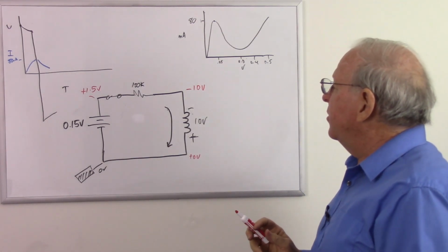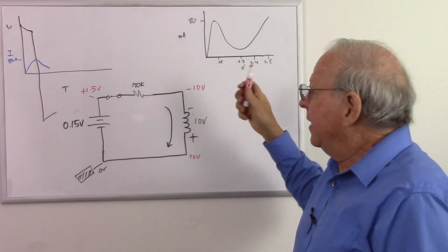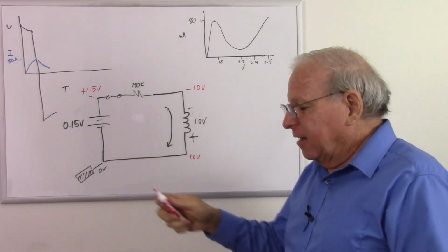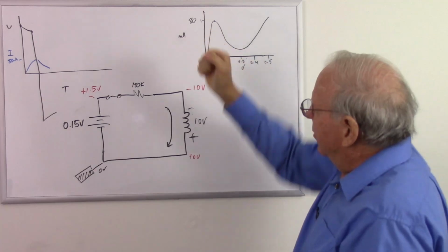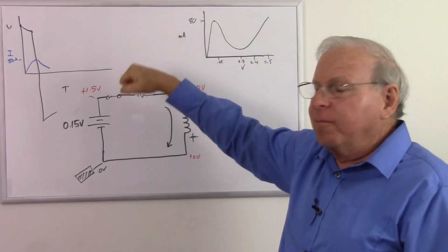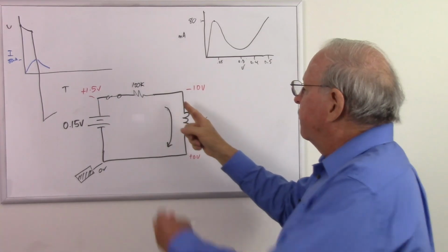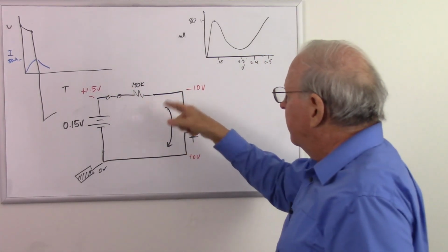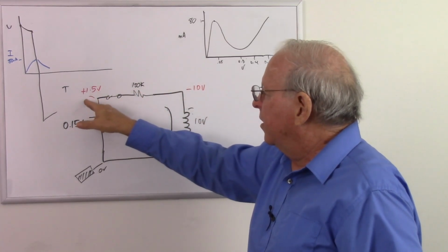So that wants to be minus 10 volts. So that voltage is trying to shoot way, way up. The little green man in the tunnel diode is saying, oh, well, yeah, but your current has to go down. It's increasing its impedance tremendously, trying to force that current down, as this is trying to force the difference in voltage across here up. What's the difference? It's 11.5 volts. Minus 10 volts plus 1.5.